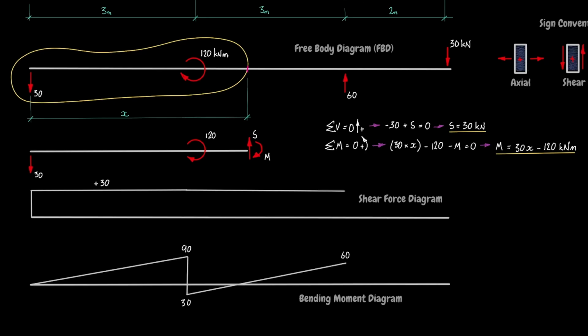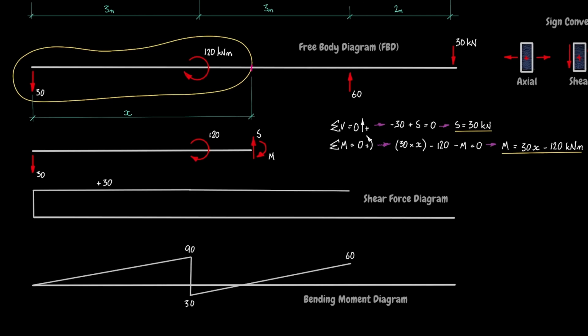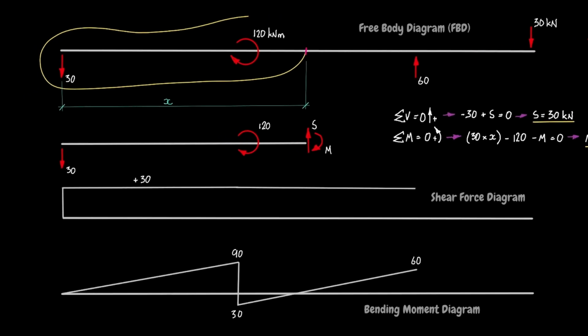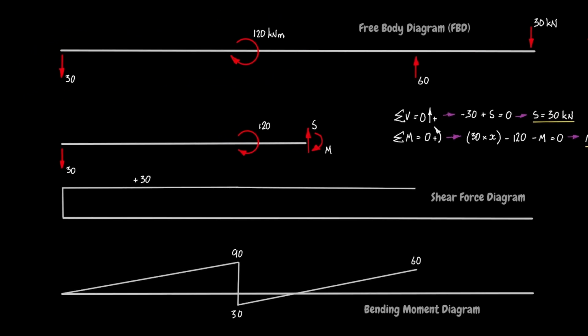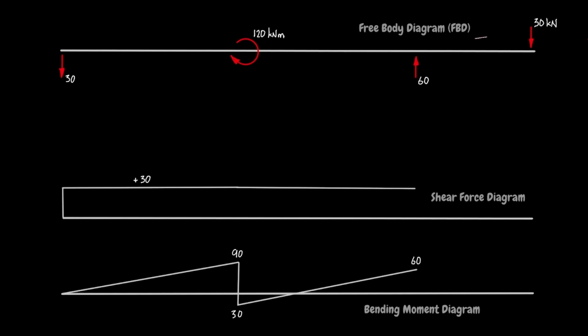All that is left is to find out what's happening between C and D. Tidy up the screen, then draw a free body diagram bubble that cuts the beam between C and D. Note that the bubble encloses the substructure to the right of the cut. This has been done to simplify the free body diagram and calculations.